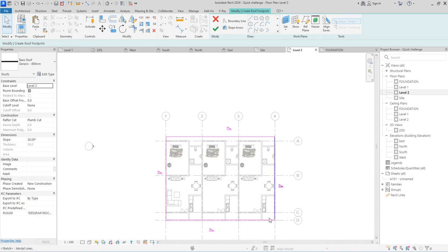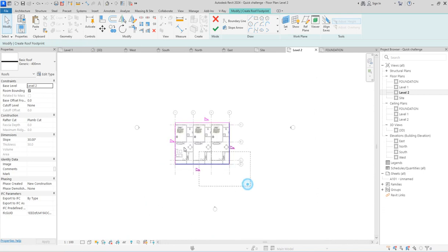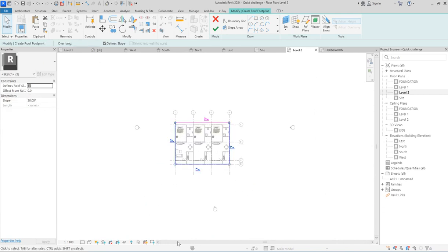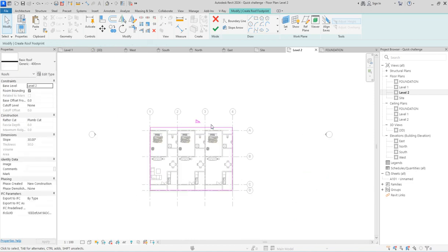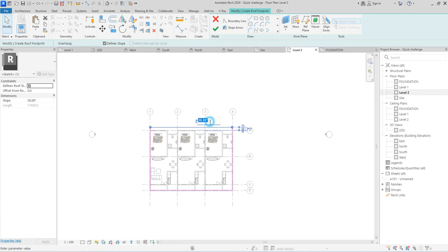So you use that and you place. So what you do here is to delete all this slope because that is not what we want it to fall only to one side. So click here, define slope, and let this slope this side. So here you reduce the slope to something like 4 so that it is flat and slants normally.